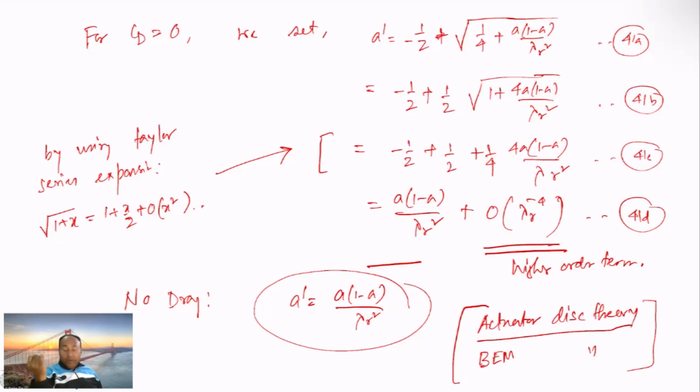But when we talked about the actuator disk theory, we have not considered the rotation of the wake, which is there, and because of that, you may start getting some performance effect. And in the wake rotation, we consider the rotation of the wake in the system, and that's what we talked about in the BEM theory, where you consider all these things.